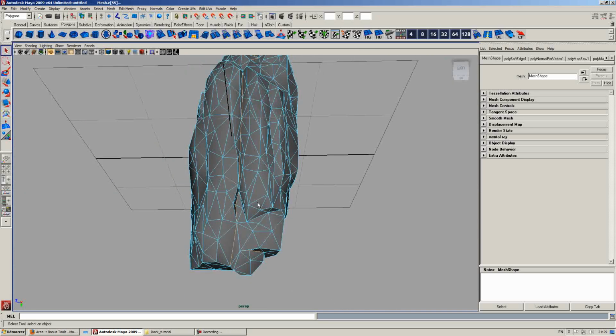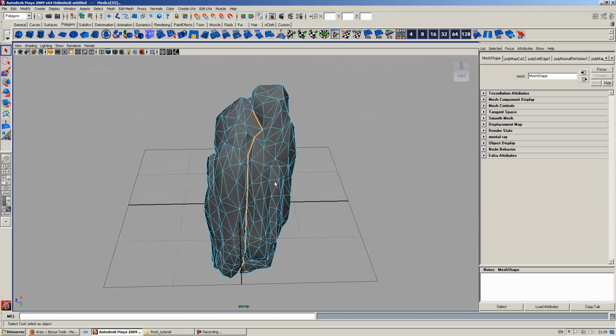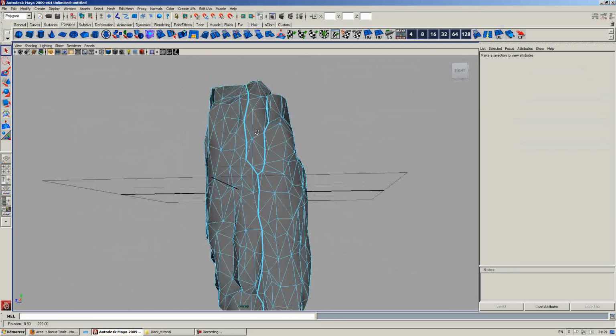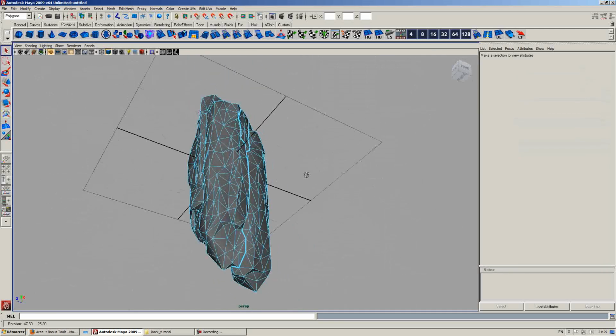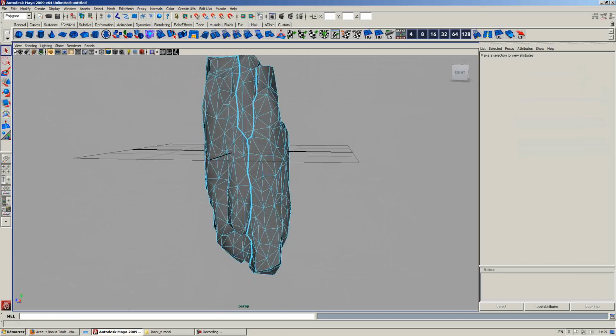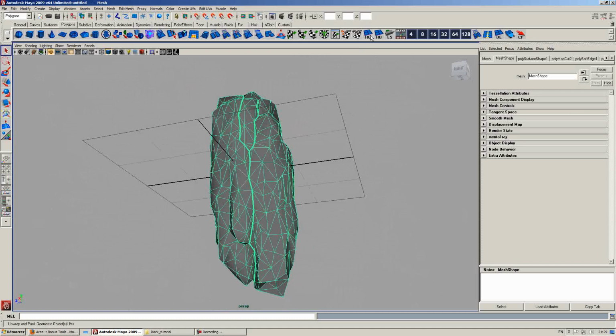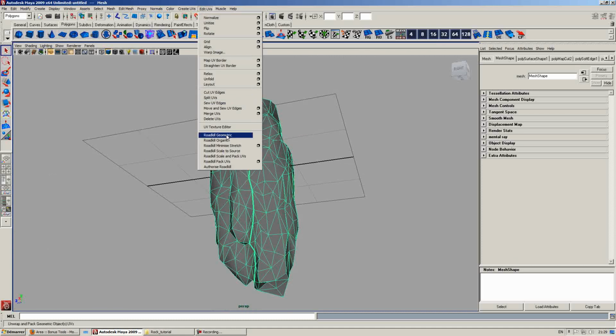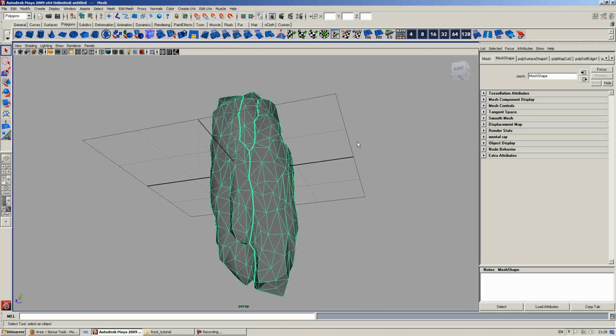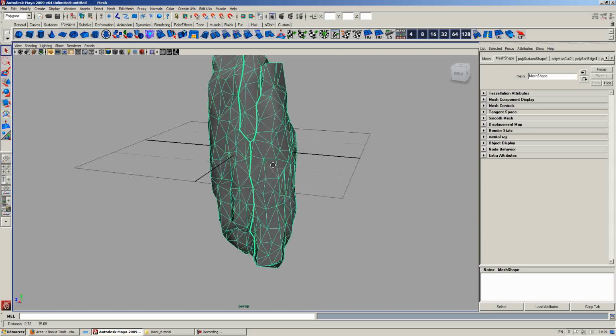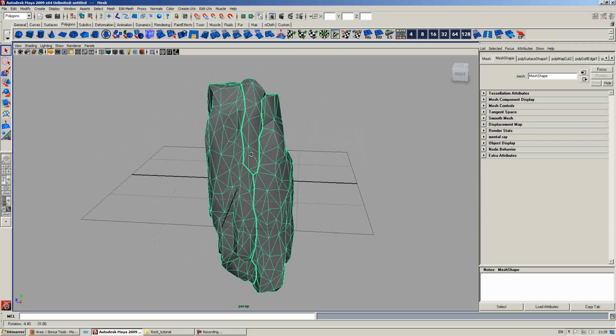Now once you're done selecting the edges, you could just cut, and you can see that there's actually a seam that has been created. So what I'm gonna run now is I got the RG and RO. If you're using Roadkill, if you go to edit, you get Roadkill Geometric and Roadkill Organic. These are two different algorithms for unfolding your UVs. So it automatically does the job for you, and it is extremely fast. That's why I like using Roadkill.